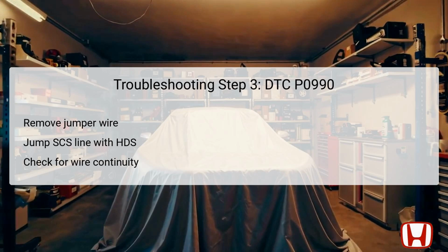The first point is from the transmission fluid pressure switch, E, 6th clutch, 1P connector number 1, and the second point is PCM connector B, 51P, number 28. Confirming continuity here is crucial. If it exists, the OP6SW wire is deemed functional, necessitating a PCM replacement if the issue persists. If there is no continuity, this indicates an open circuit in the wiring that should be repaired between the transmission fluid pressure switch, E, and the PCM.